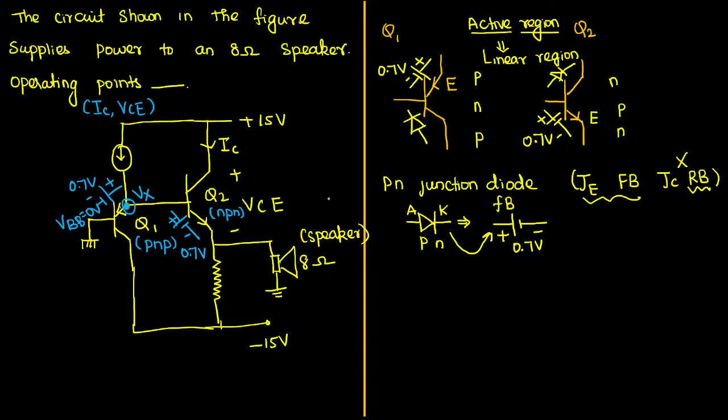Okay, sir. So I'm just taking the transistors separately. Clearly focus on the circuit one more time. They have clearly told this is the emitter junction. I just wanted to know the voltage at this point. We can cross this terminal, we know. So this is plus minus 0.7 voltage. It is connected with the ground. So if it is connected with the ground, this voltage is going to be 0.